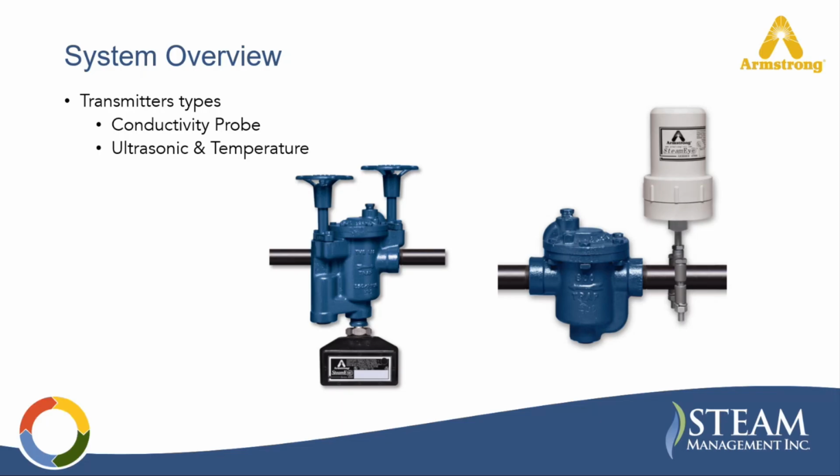The conductivity technology is primarily used with Armstrong inverted bucket steam traps and certain condensate handling equipment where the liquid level inside the equipment can be monitored directly. The ultrasonic and temperature technology is designed to continuously monitor virtually any type of steam trap. We'll cover that technology later in the presentation, but let's start by taking a closer look at the conductivity monitoring.